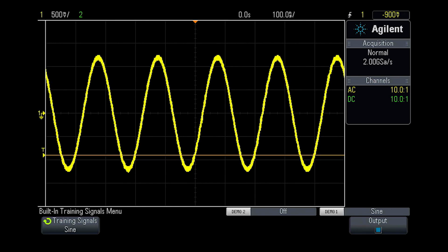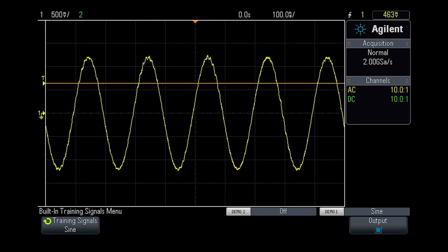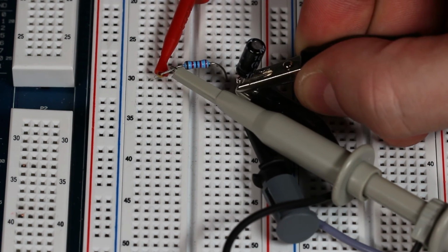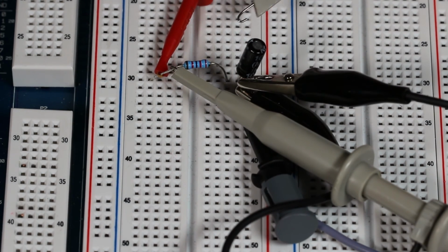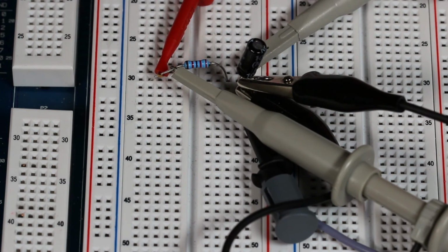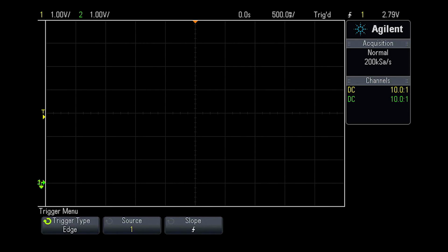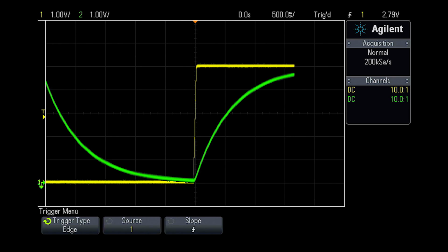it to the display. In this example, a simple capacitor and switch circuit has 2 probes attached so that the voltage can be measured across the capacitor and across the switch as it's closed. When the voltage across the switch exceeds the trigger point, 0 volts, the oscilloscope starts capturing the signal.